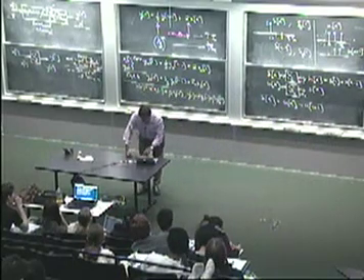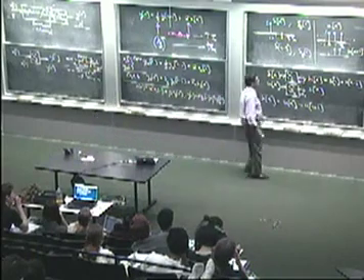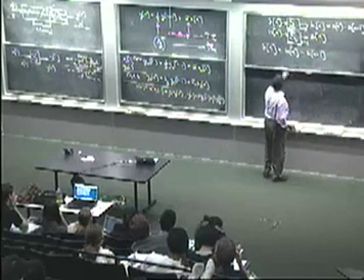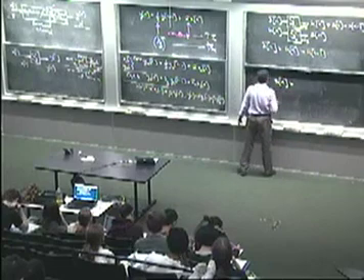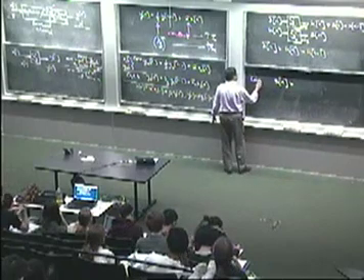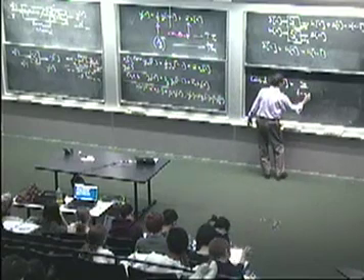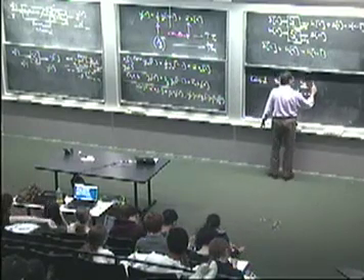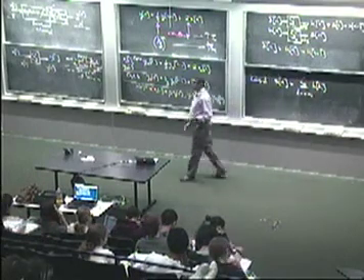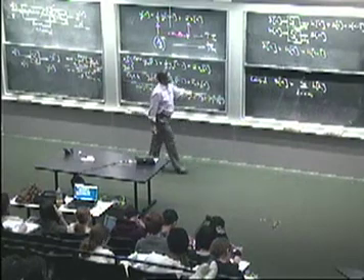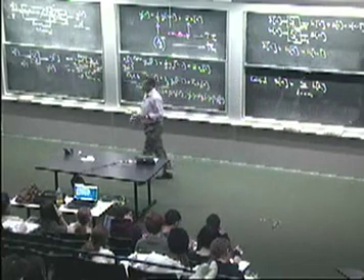Okay, so this is an identity we'll be wanting to play with a bit. So let me put it up here. So the step response, let's say for a causal system, is going to be summation from k equals minus infinity to n of h of k. So I take all the values of the unit sample response up to the present time and sum them together to get the value of the step response at the present time.